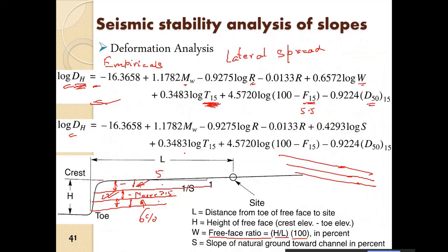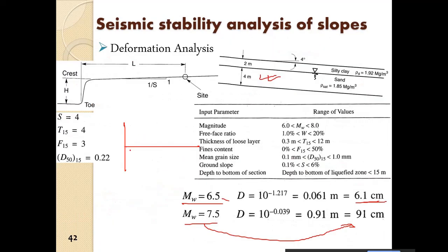So if we compare that with that, we can consider that in magnitude 6.5, the maximum acceleration was significantly lower than what it was in 7.5, and obviously in 7.5 magnitude the number of equivalent cycles will also be more. So you can see a significant amount of displacement. So this earthquake may have caused failure in the dam. That idea we have to inculcate, we have to visualize that.